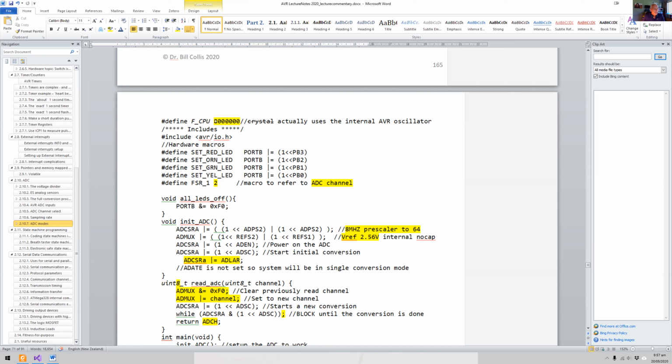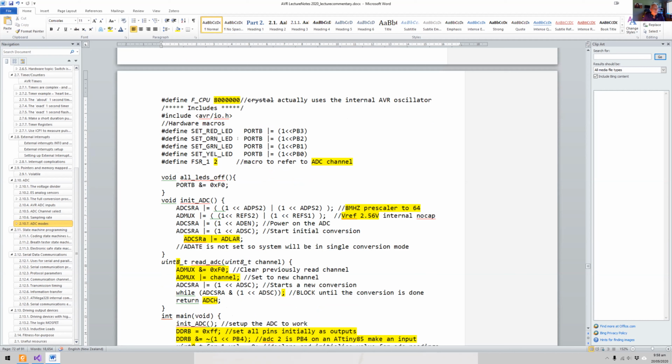subtly differently, perhaps on a different microcontroller. Now that board I had didn't have a crystal. Okay, all of these AVRs have internal oscillators you can use, and I've got it set up to be an 8 megahertz oscillator. So in this case I'm using 8 megahertz, and it's coming from an internal oscillator in the microcontroller. I've got my LEDs configured. These are just some port Bs.